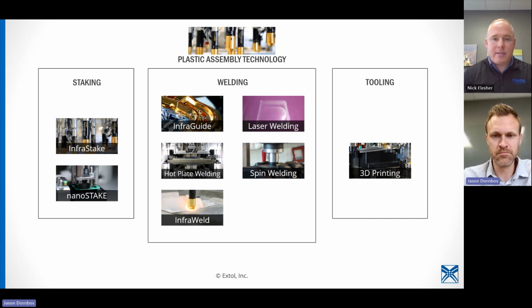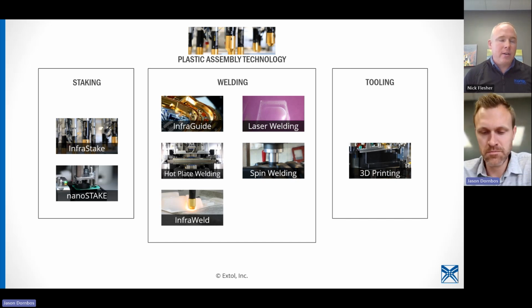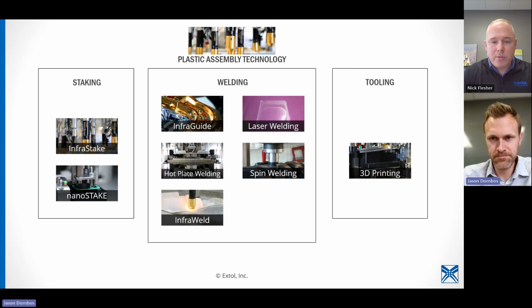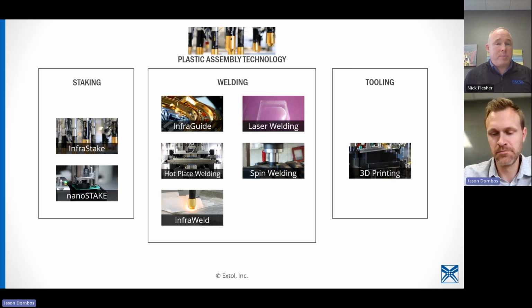The second tool is we do have compatibility charts. Not all plastic needs the same plastic to weld together. There's a family around polycarbonates, ABSs, PMMAs, all those weld in various strengths and whatnot. So we'll do a follow-up with those two things, but those I think are more weld technology specific. I'm wondering if Aaron has more of a question about all technologies.